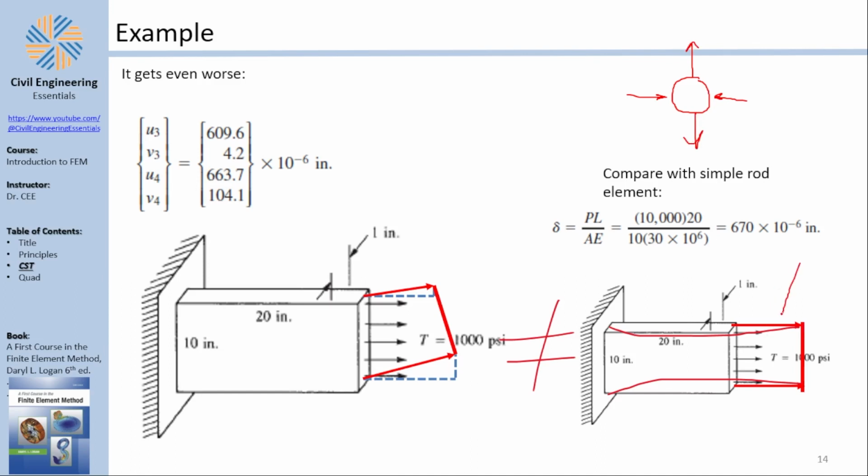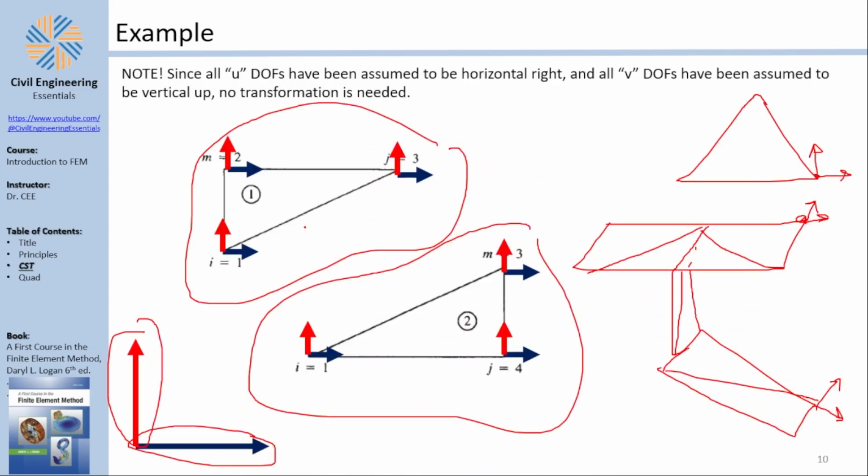If you are pulling, or basically applying tensile stresses, on a bar, it should get thinner at the edges, and this edge should move the same. Well, now it doesn't, does it? No, it doesn't. It does not because, simply said, BSc level, because of the weakness of the CST element. MSc and PhD level, it doesn't because it is mesh dependent.